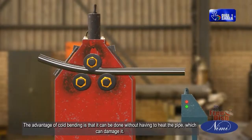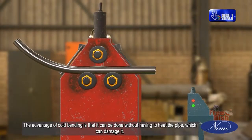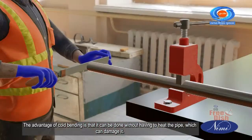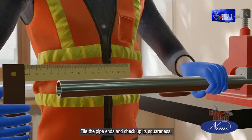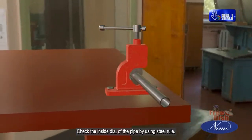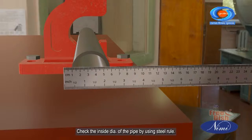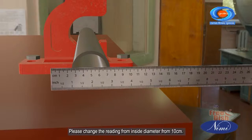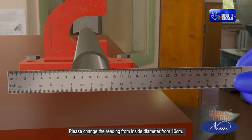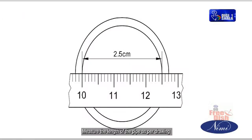The advantage of cold bending is that it can be done without having to heat the pipe, which can damage it. File the pipe ends and check the squareness. Check the inside diameter of the pipe by using a steel rule. Please note the reading of the inside diameter, 10 cm. Measure the length of the pipe as per drawing.